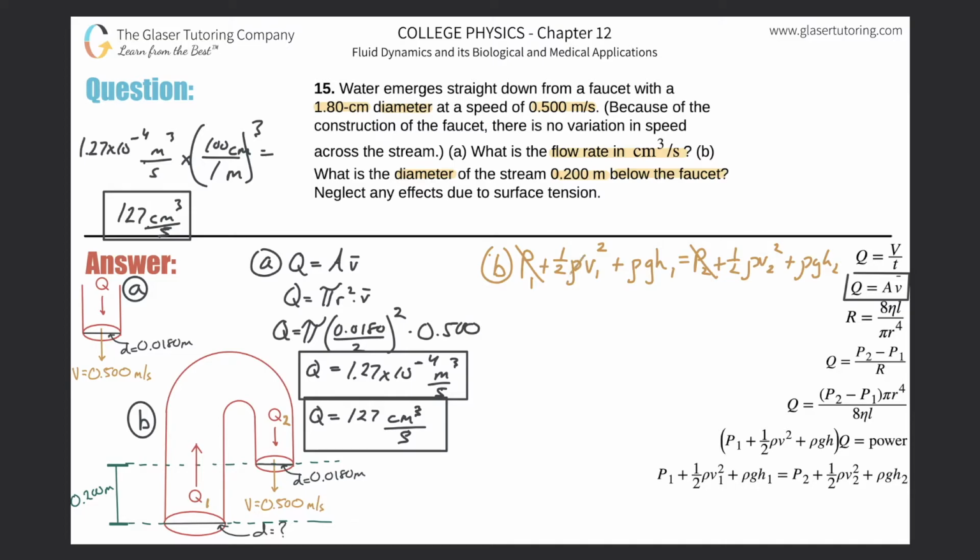What that means now is, look, the density was in every equation, so I can cancel that out, right? So now what am I left with? Well, now I'm left with this. So I have 1/2 v1 squared plus g times h1 will then equal 1/2 v2 squared plus g h2. Now, how about these? Okay, great. So we want to find, what's the variable of interest? The variable of interest is v1, right? I want to find, it is v1, but it's indirectly v1.